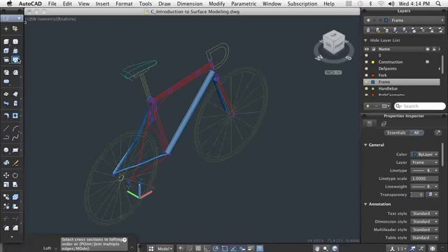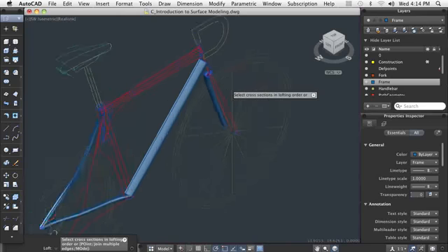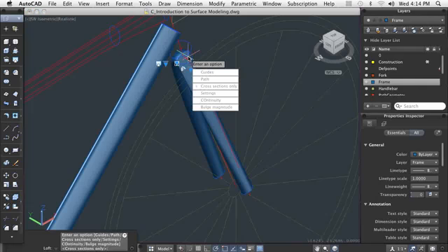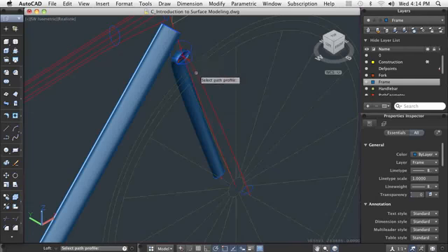First, let's complete the front fork tube using a basic loft and path method. I've drawn the shape at the bottom of the fork on the right side. Now, I can match that shape up to existing geometry so I end up with a uniform looking part. After I add the path, I can control the uniformity of the tube with a simple 2D spline.